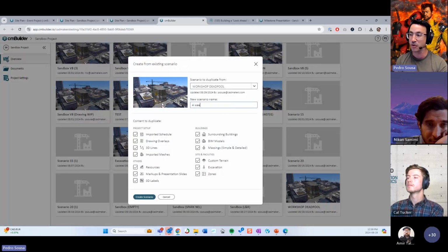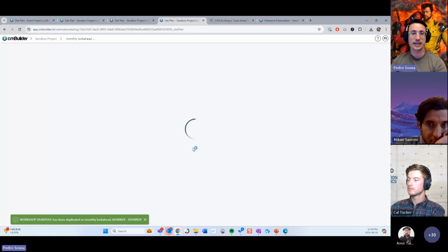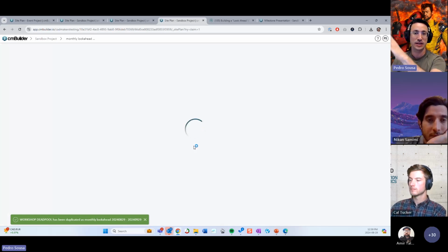and then from this scenario you can do a 4-week look ahead for a different period, like from, I don't know, today up to, I don't know, a month. Let's put it like that, right? So this is a month look ahead. So you can do something like that. And then on this new scenario that I created over here, I will go in and update the schedule, update the file that is connected that created my schedule.